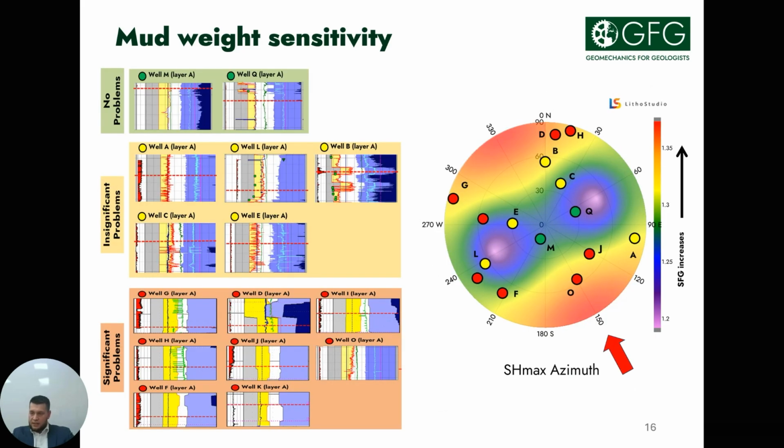The sensitivity analysis can be used to calibrate the geomechanical model and refine the SH max. The essence of sensitivity analysis is that the reference layer is taken. All drilling events, well survey, and other materials are analyzed for borehole instability. For each well, the breakout shear failure gradient is calculated for the reference layer and compared with the actual data.